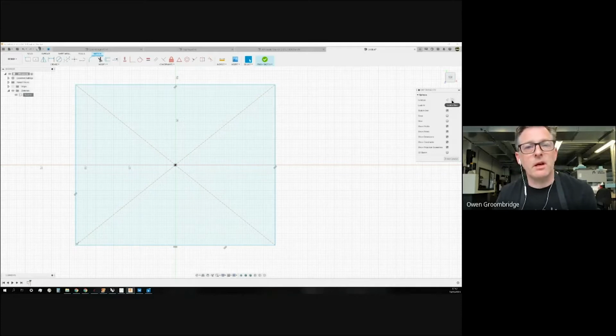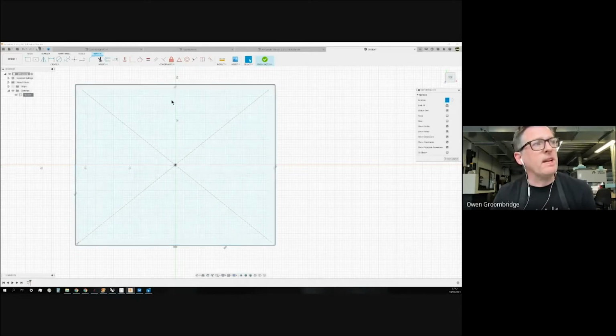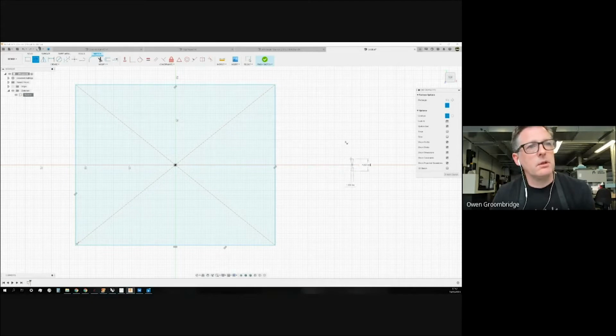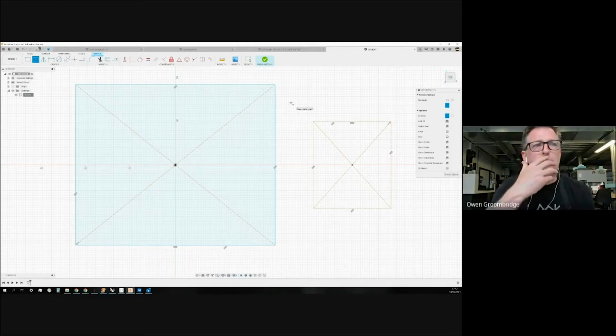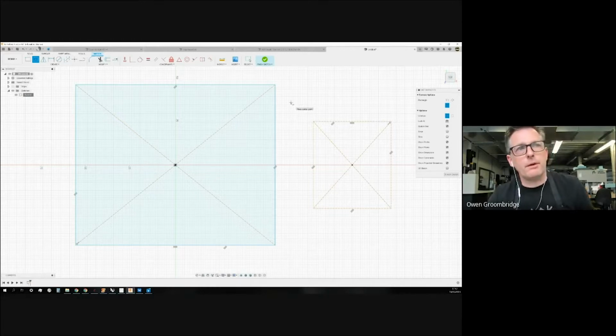And center lines have a slightly different symbol. We'll have a look at it in a minute. But for example, you could have that on all the time. And anything you drew within sketch mode, like another rectangle, sure enough will form these construction lines. And as I might have mentioned before, construction lines are a way of creating scaffolds. So, as it were, they're really, really handy.